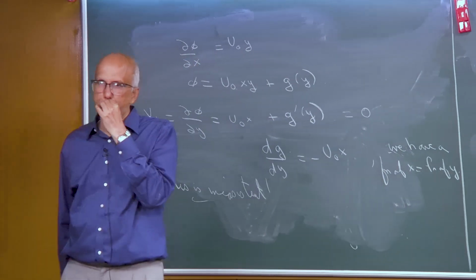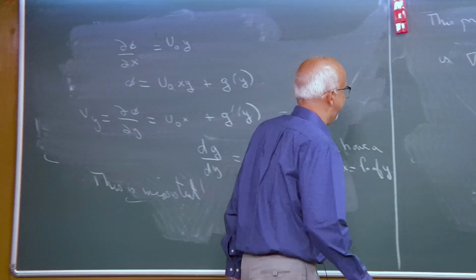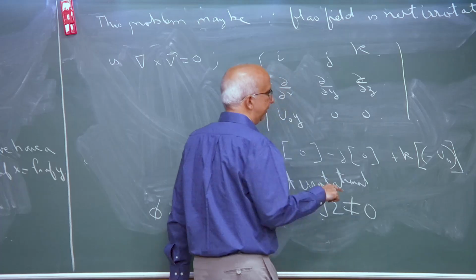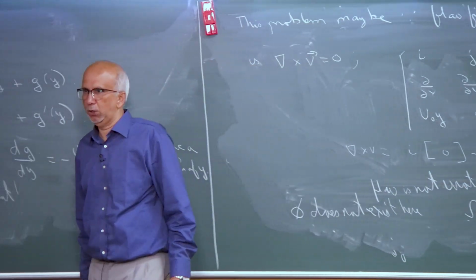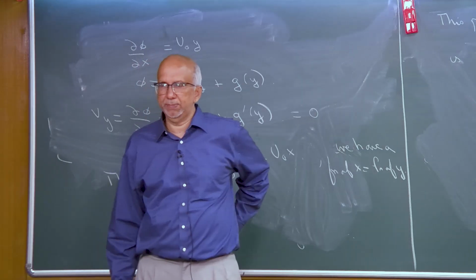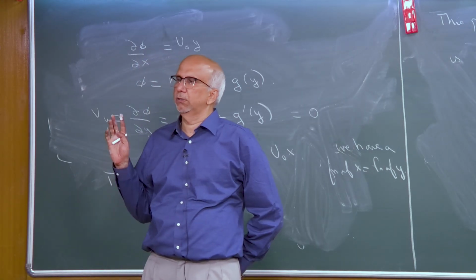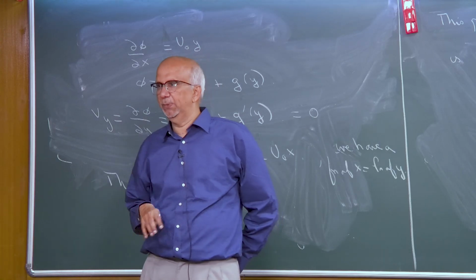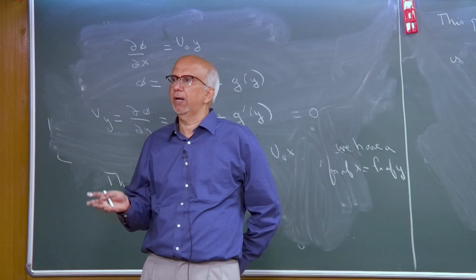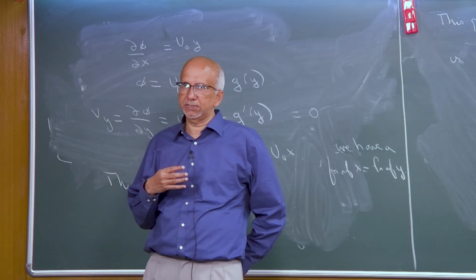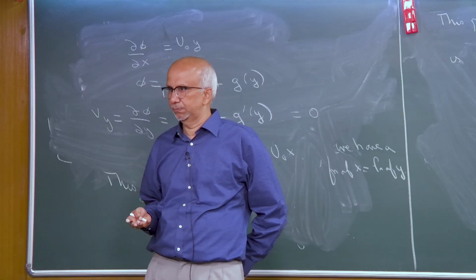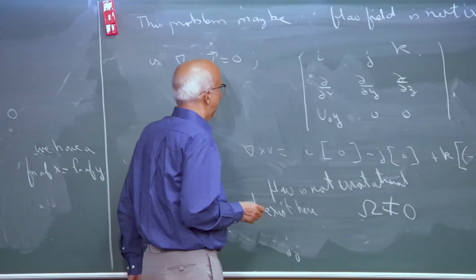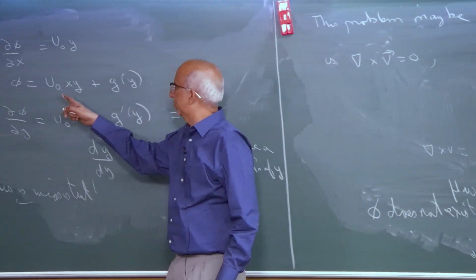Okay. So, the point is, omega is not equal to 0, there is a vorticity associated with it, curl of V is omega. So, that is basically the point. The flow was actually one dimensional, but because it is a subset of 2 dimensional, I can get my streamline, but I cannot get my potential function in this case because the potential function does not exist. So that is the reason when I was trying to find the potential function I could not find it.